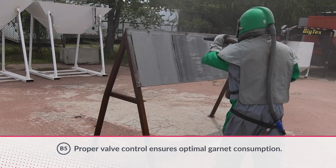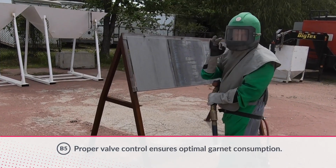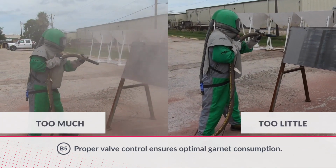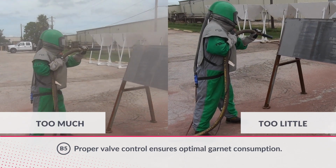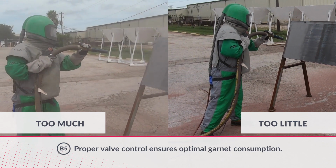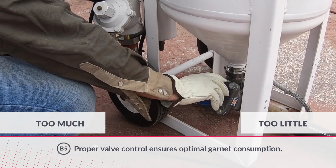Test production rate by blasting. You will hear a chugging sound and notice excessive dust if you are overfeeding the garnet. If you are underfeeding the garnet, you will not be able to clean the surface effectively. Having the right abrasive metering can help reduce garnet consumption rate.